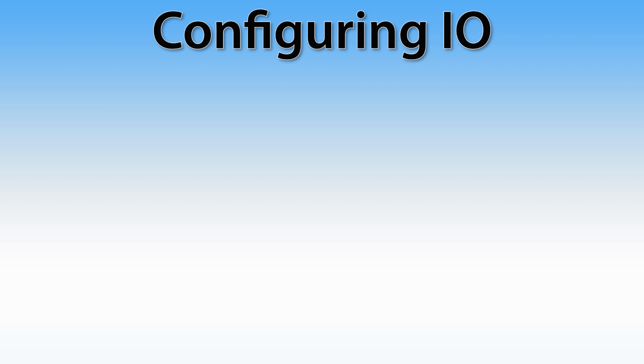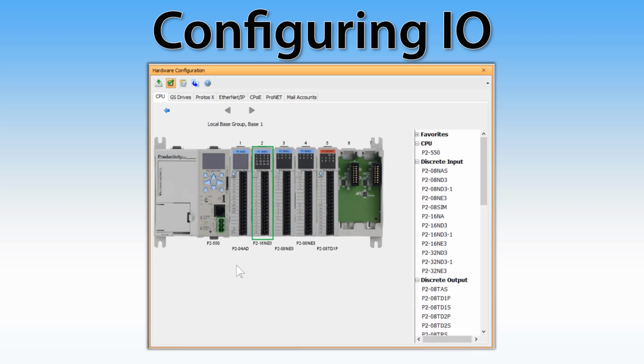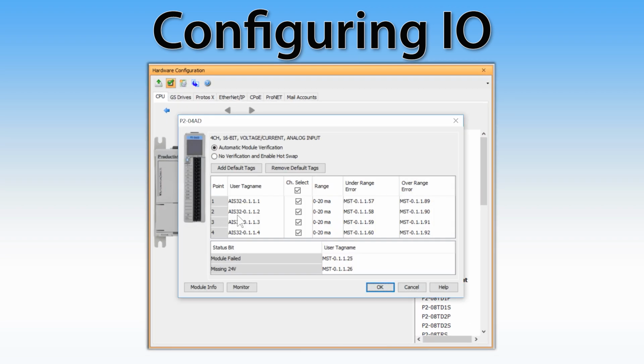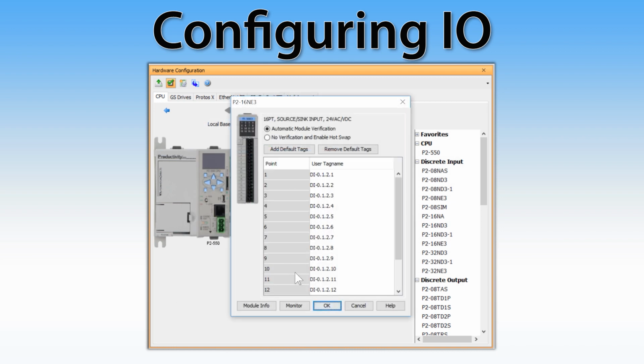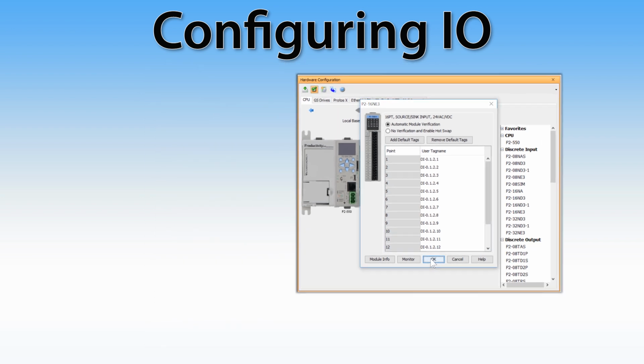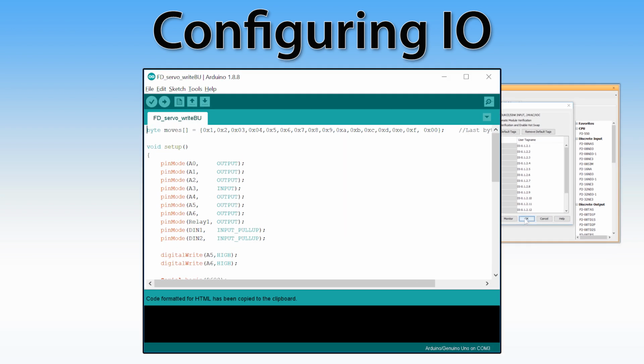Auto-config of I/O. With most PLCs, before you even start a project, the I/O is already mapped to a variable, so the configuration of the I/O is already handled without the programmer's intervention. With Arduino, you will need to set up the I/O to be read or written to.